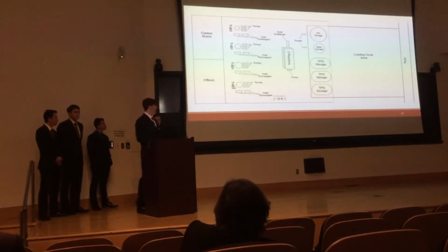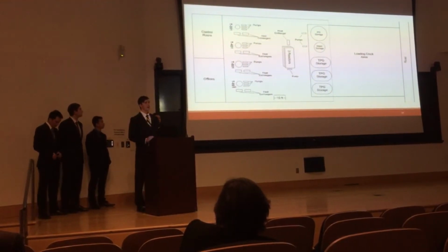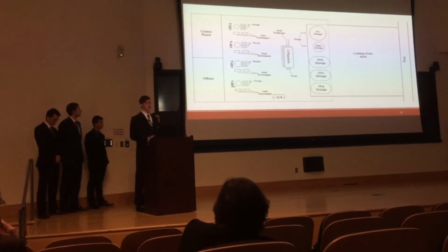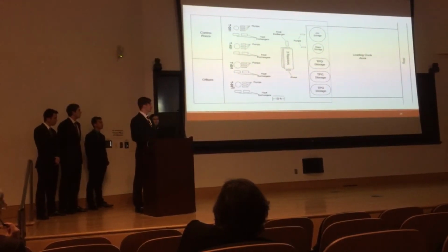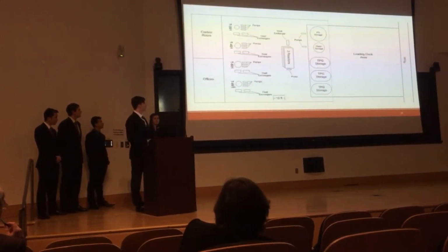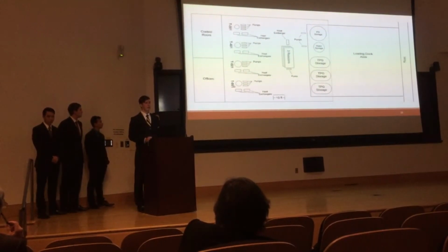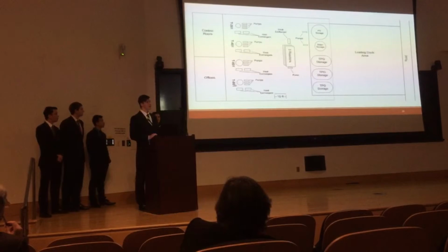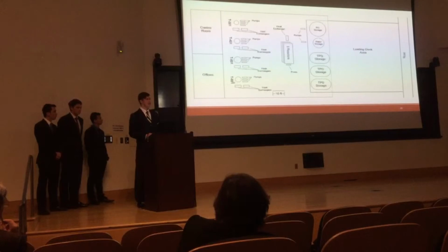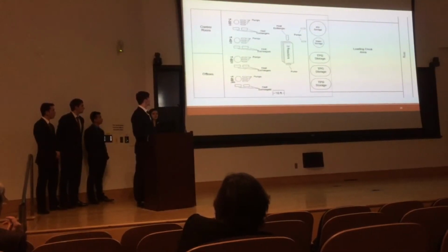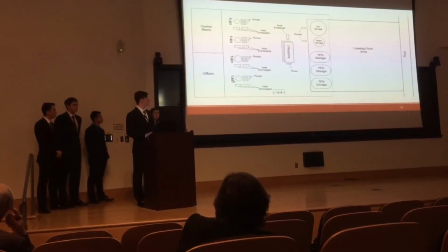Looking at our plot plan, all 3 reactors are stacked on top of each other, meaning that if our CO2 foam sprayers are activated due to a runaway reaction, all reactors will be shut down immediately and the process will stop completely. Additionally, our PO storage tank is located near the loading dock area, so in the event of a chemical spill or a fire, any chemical cleanup teams or fire companies can easily access the area and take care of any problems necessary. PO storage is also located very far from the control room where any people will be located, so it keeps them at a safe distance from this.